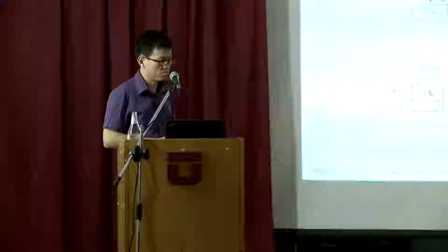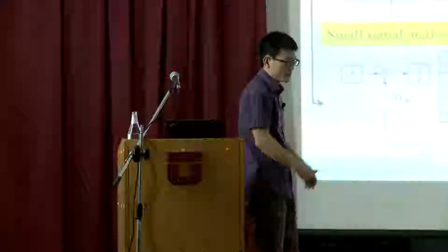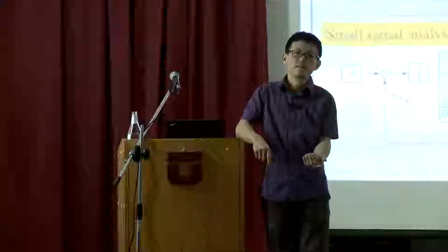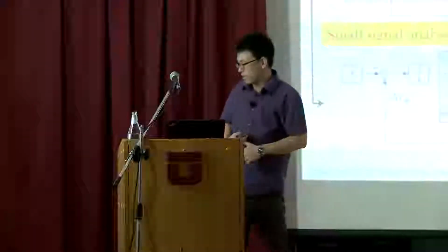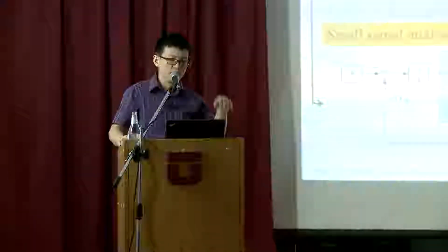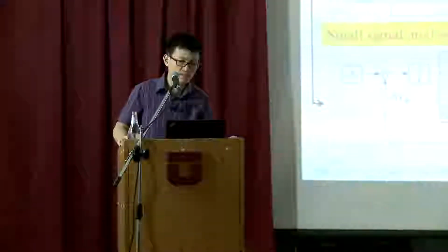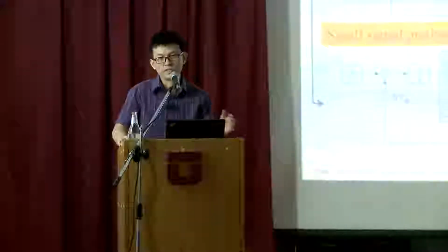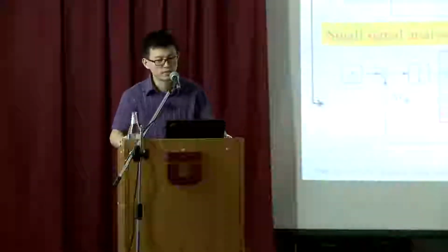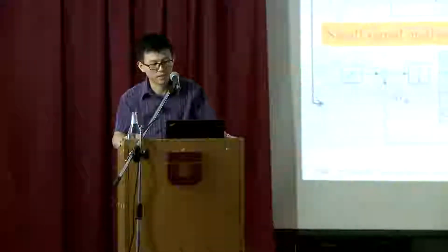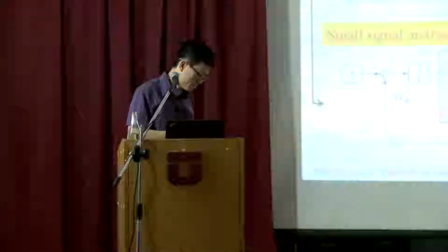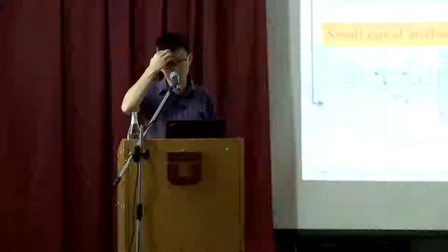If you study the stability of a system, most likely you will end up with 2 ways. One is to use the state space concept, where you have x dot equal to Ax plus Bu. This is a very standard one, and you study the eigenvalues of this matrix A. Another method, of course, is using the impedance, which we call impedance analysis.